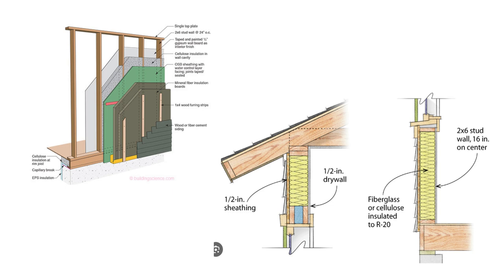Here's some simple images. So up here we are showing a method that's very typically used in the United States and Canada. So some kind of wood member. In this image, these are 2x6s. 2x4 is very common. That means it's 2 inches thick by 6 inches or 4 inches deep, and then usually 8 feet tall. Could be taller. Inside of that, right here, we've got insulation. This is referred to as cavity insulation.